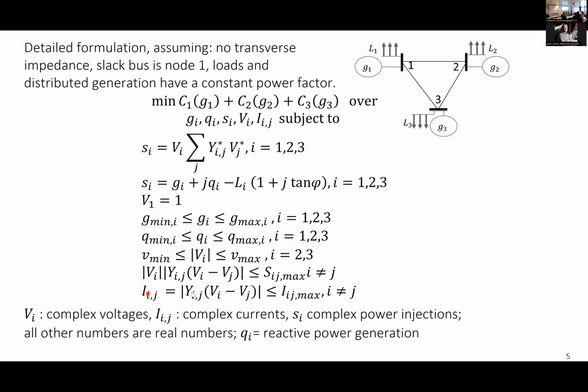The thing that normally makes sense is the constraint on the current, because the physical thing that happens on the line is the current. It is the current that makes the line heat up, and when the line gets too hot, if it's an aerial line, it will get longer. And when it gets longer, it might touch trees. So one of the problems is that. So we should not get it too hot. And second, the insulators also will get hot and might get damaged here. So as you can imagine, any system has a thermal capacity that cannot be exceeded. This is captured by this formula here.